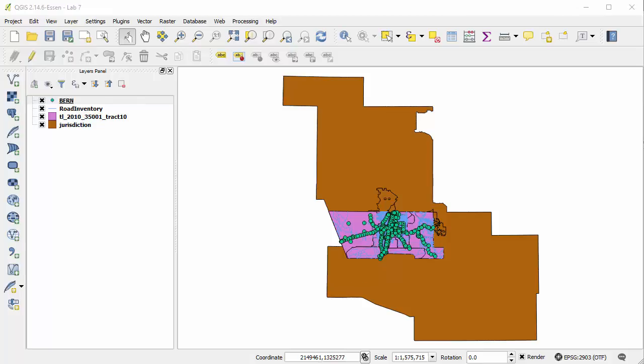Okay, so projecting on the fly is fine for cartographic purposes. However, when conducting a geospatial analysis, the data layers involved should be in the same coordinate reference system. Typically, data layers will also be clipped to the extent of the study area to reduce rendering and data processing time. These procedures are often referred to as normalizing your data. For the typical analysis, a majority of your time is spent on obtaining data and normalizing it. Once all the data is organized and normalized, the analysis can proceed.